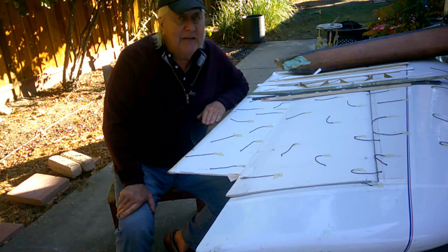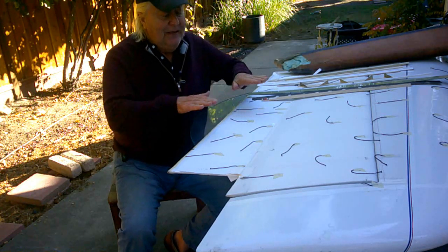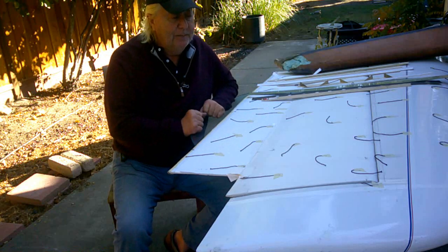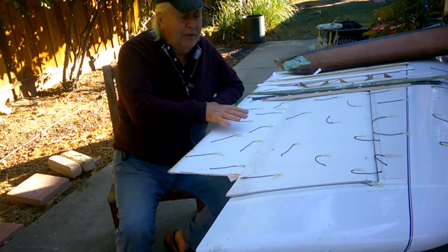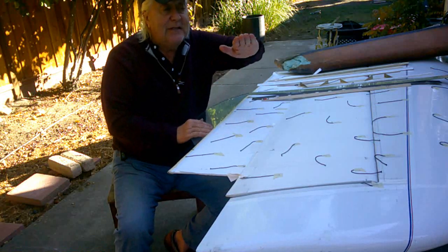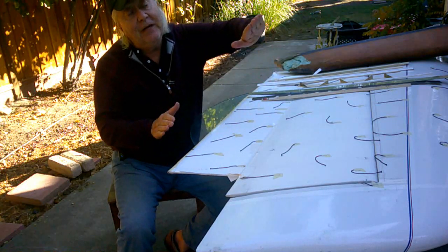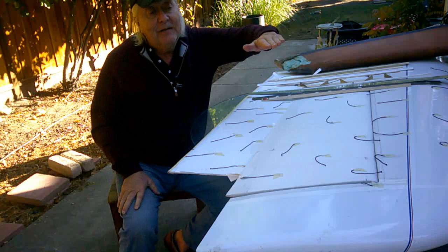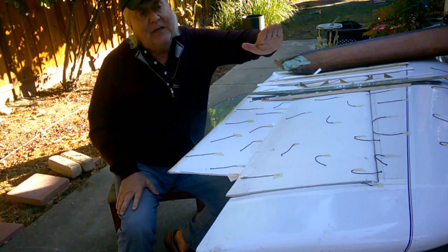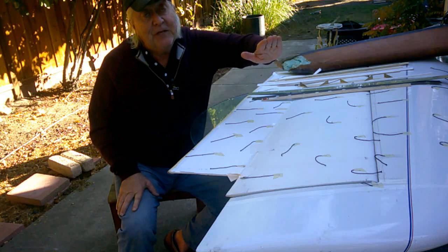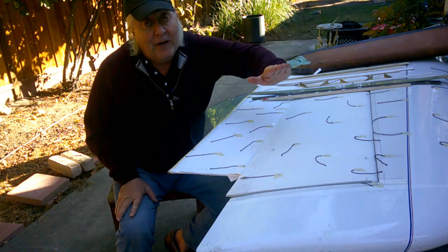And it's a double whammy, it's really bad. As the elevon goes down, the flow begins to separate, and of course the down elevon is lifting the wing, so if I want to roll right, the left elevon is down, and that creates more lift on that wing and begins to lift the wing. But if the flow starts to separate, you lose lift on that wing.